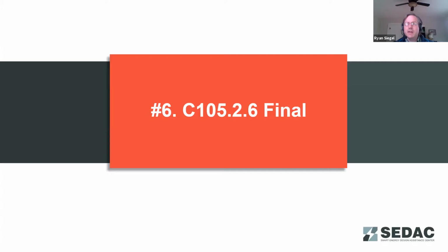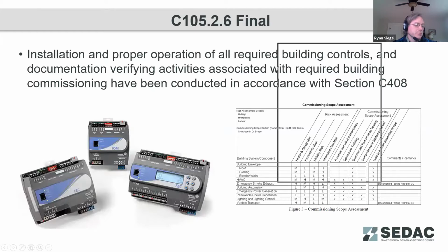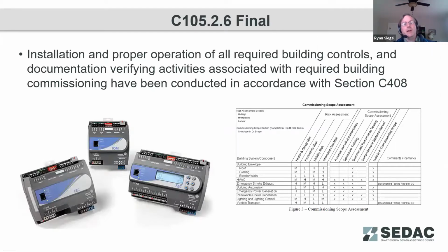So yeah, the lighting and electrical inspection is going to be fairly brief. The one other thing that I should mention in here for the electrical is pertaining to elevators: checking to make sure that the elevator shut off occurs, which I believe is within 15 or 30 minutes of there being no one in the elevator, that the lights and fan shut off when the doors are closed.